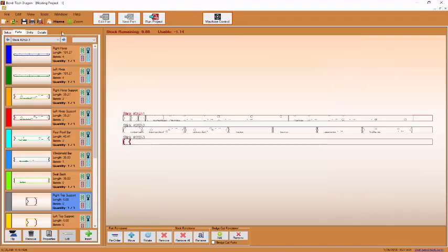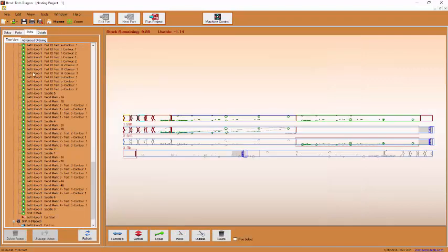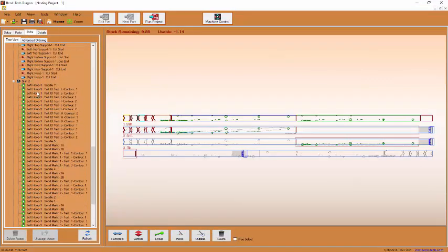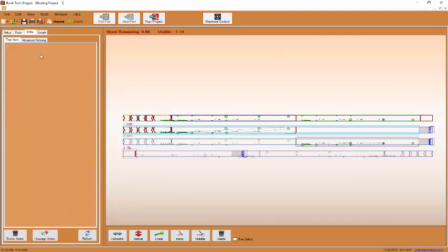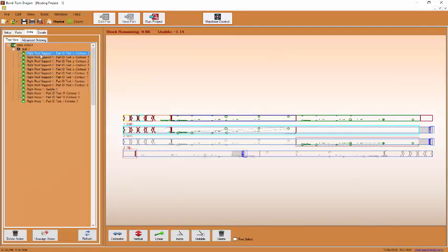Couple other things to address, I suppose, would be in the shifts tab. If you ever find that you don't want all this marking done on your machine, on these parts, that's totally fine. You can click on them, you can reorder them either by clicking and dragging, or you can simply click delete on each one, and it will send them to the unassigned actions at the bottom of this list.